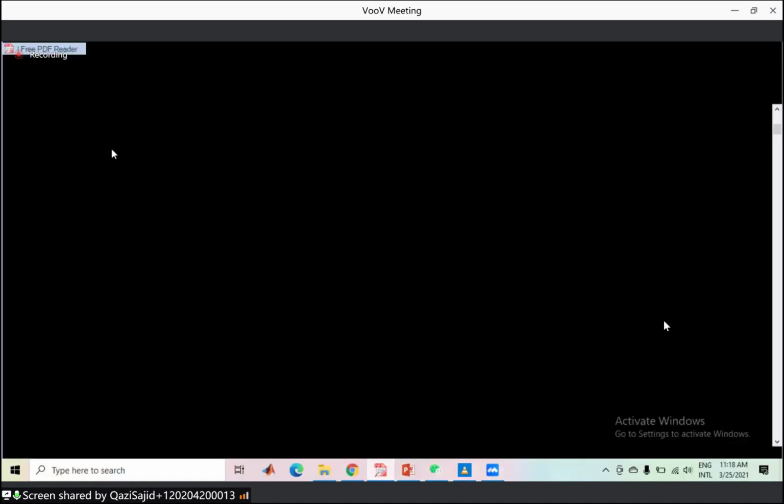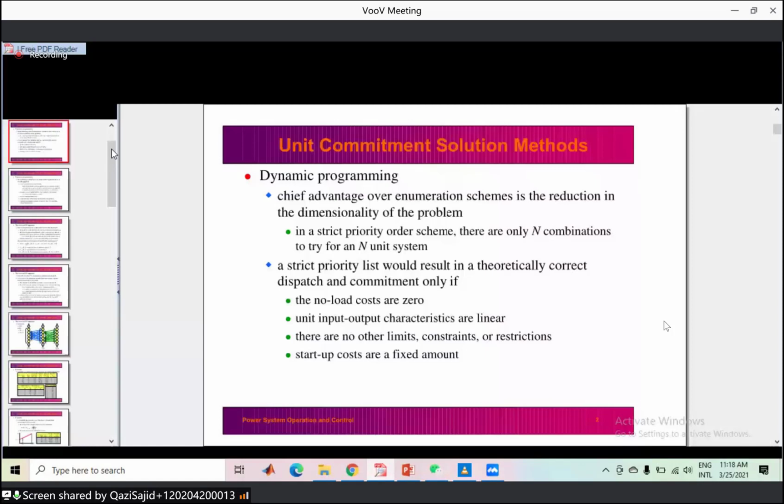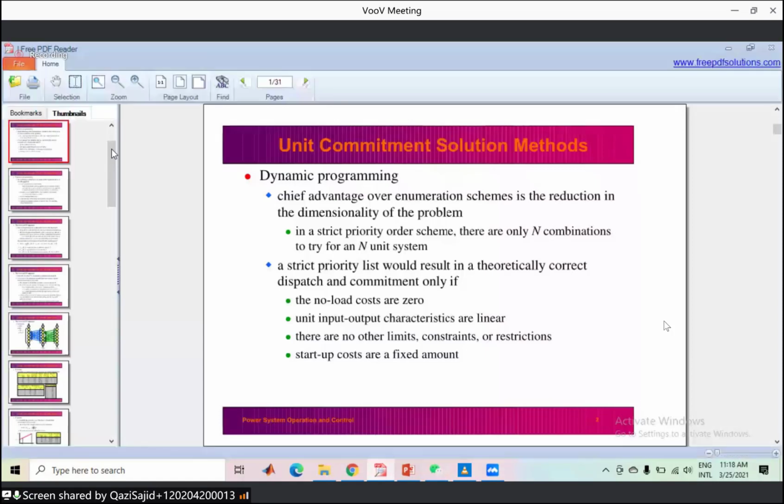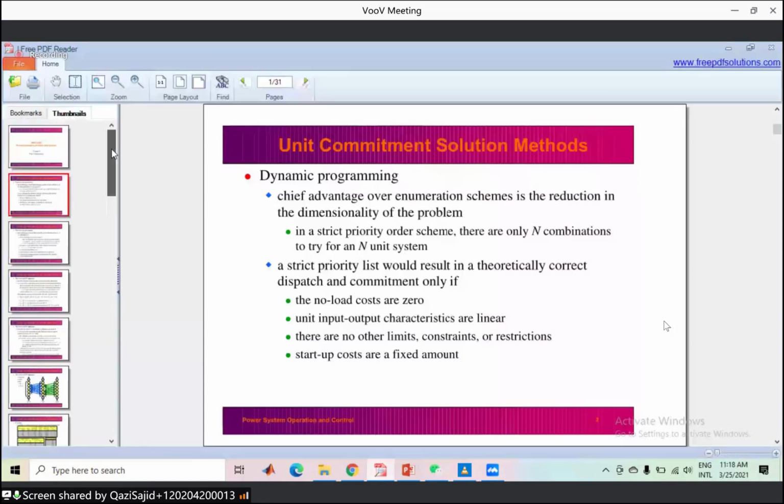Let's have some review on what is unit commitment, then we will move on to its methods. Unit commitment is an optimization process where the system operators choose the production unit state, on or off, and their production level in order to minimize the production cost, system price, or social welfare, and to meet demand through a period of time, a day ahead or a week, subject to ramp rates.